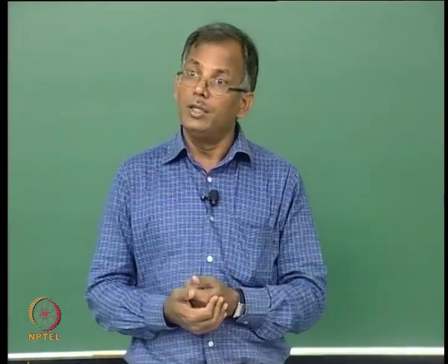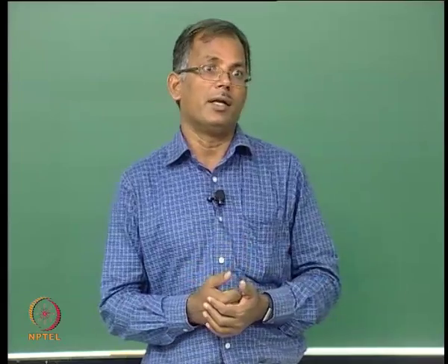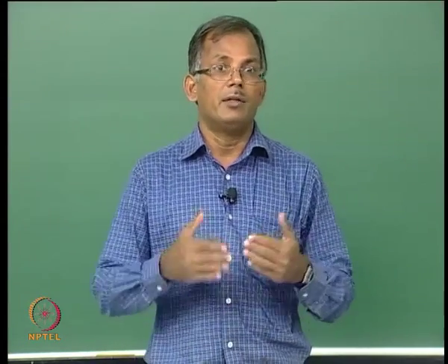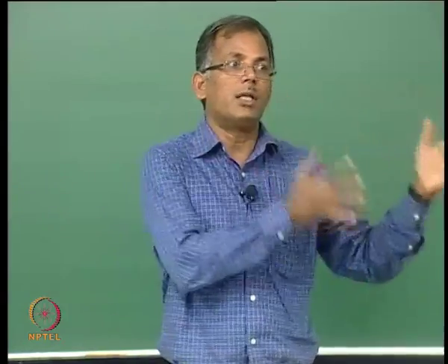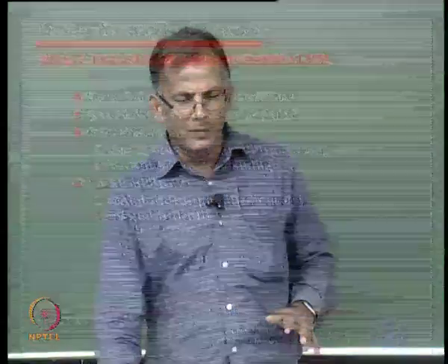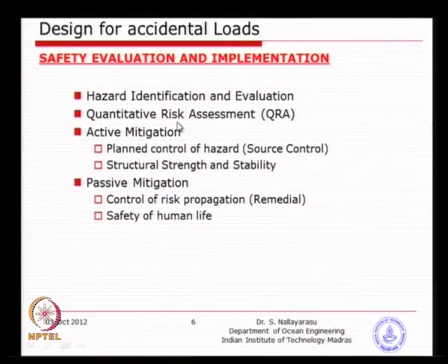So, basically you need to evaluate quantitatively, not only that, the frequency of occurring, how fast, how quick the repetitive nature of this fire can occur, which could actually give you a feel whether you should include it in the general class of loading or it should be the special class of loading. So, quantitative risk assessment is part of any project, whether it is an onshore building, bridge, offshore platform. You need to evaluate the risk, quantify them, and then take a call. For this risk, we do not want to call it a general class of loading, we will exclude it from general design, but you can actually go for a special design.